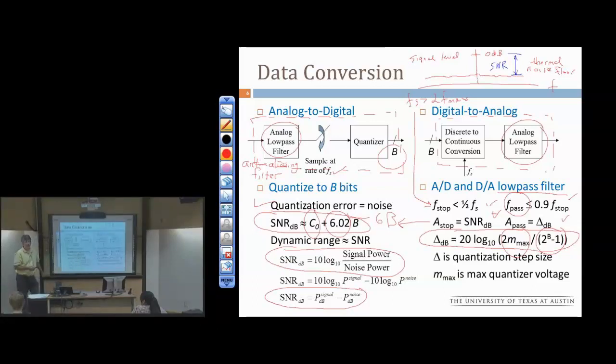On that midterm, there was a question where you had to do this with QAM and they used 3 dB per bit instead of 6 dB per bit. I understand it has something to do with the fact that, since the signals are out of phase, you can represent 2 things at once. But I don't quite understand why that would be less SNR, because you're transmitting more. Is it because you have so much more power in the signal that it gives you a higher SNR?